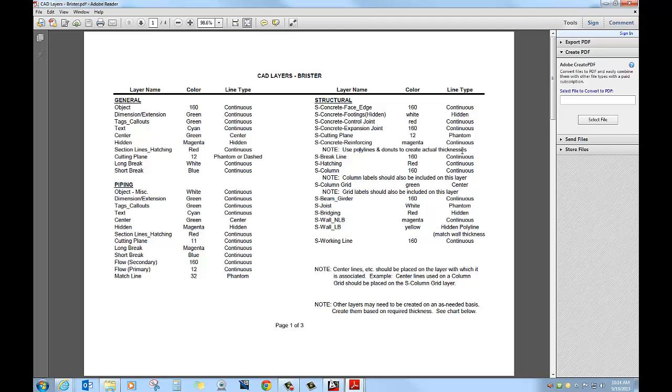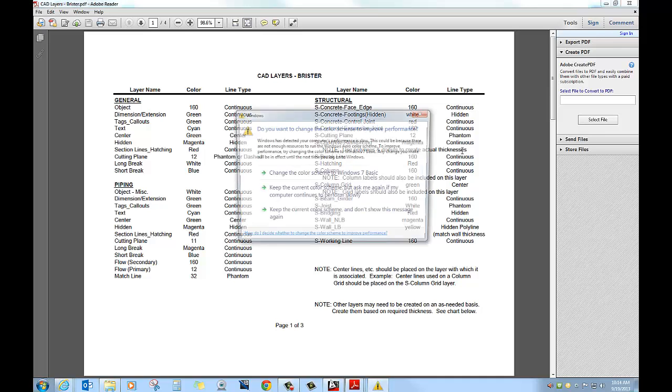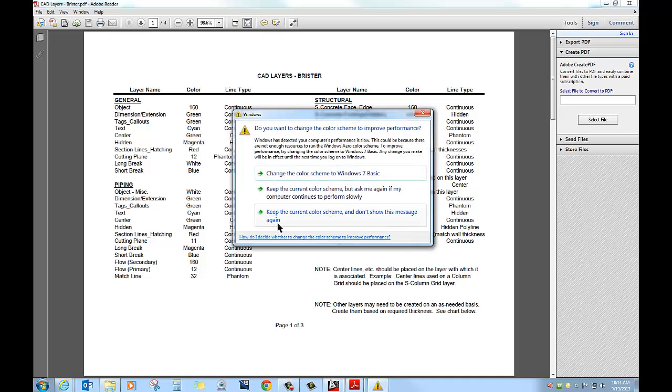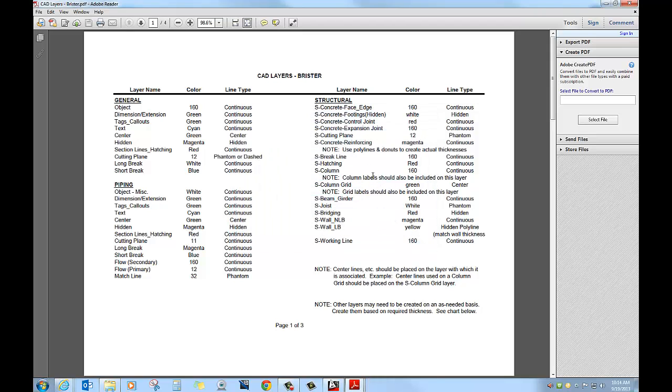If I'm showing a piece of rebar running horizontally left to right on my screen, and we'll look at some of these in a minute, I want to make sure the thickness of that is a 1/2 inch. Sorry about that again. And so we'll look at those on plans in a minute. If you're using break lines, again, where an object ends and you're cutting it off and not showing the full length of it, has its own layer.